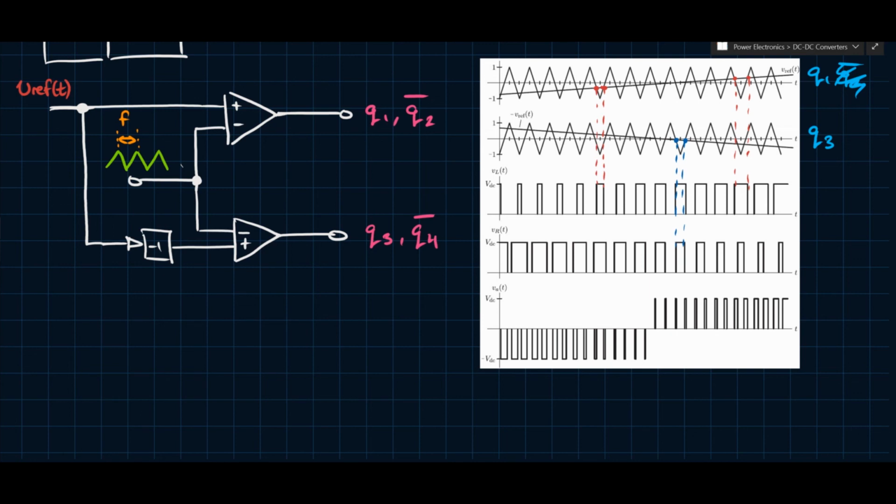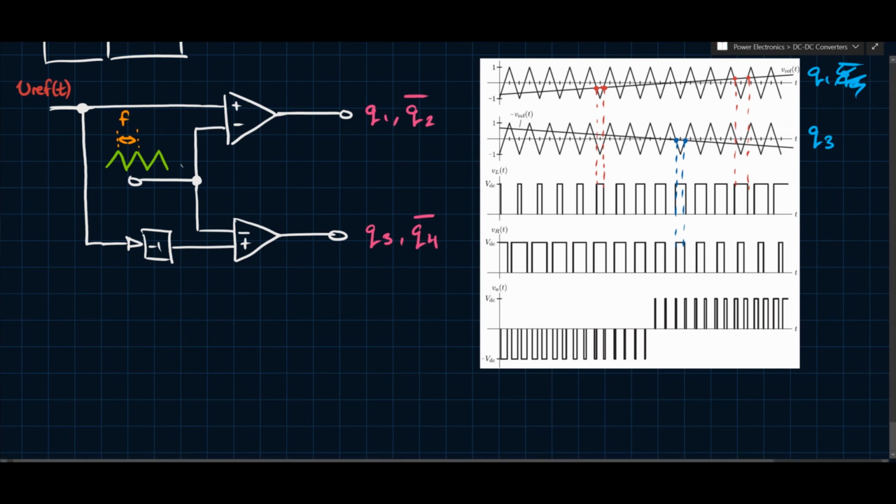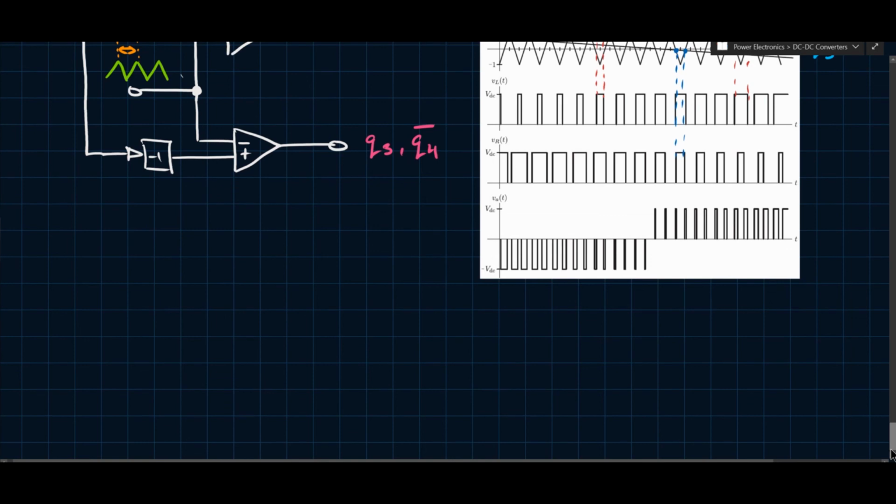So the harmonic spectrum will obviously have, well, you have the multiplication of two signals. And if you consider the multiplication of two signals, if you remember from the Fourier spectrum, whenever you multiply a signal by a frequency, you basically shift it up and down in the frequency spectrum. And then all of its harmonics will also get shifted up and down, which will produce a sort of shift in the frequency. And so if you have this type of PWM, you ensure that the PWM pulses at least are symmetric around the peaks of the carrier.